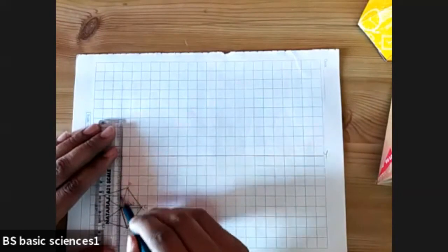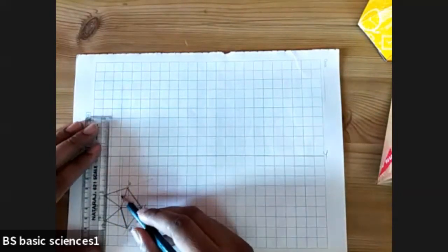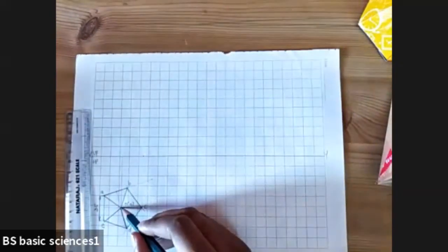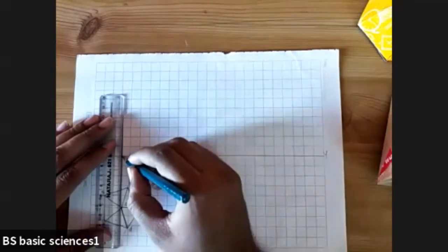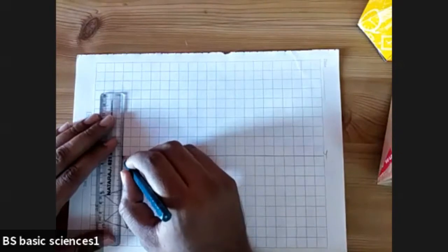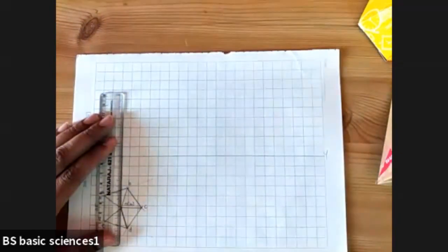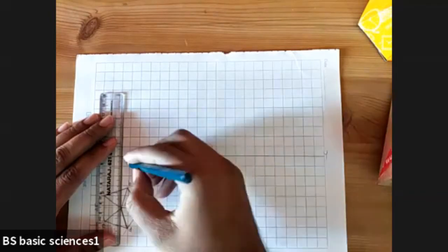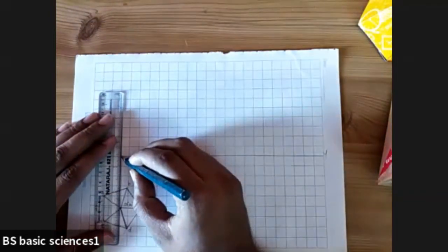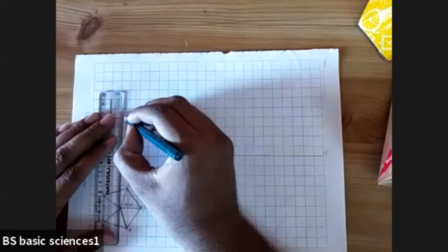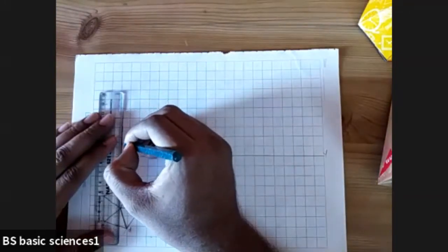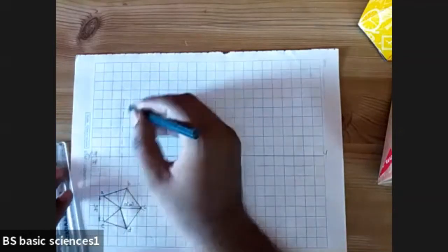First, I'll extend the axis height. From the midpoint of the axis, you'll be extending the line. And what is the height which he has given you? He has given you 50. Sorry, it is 60. The axis he has given you is 60. So it will be a thin chain line. See, I'm drawing a thin chain line.